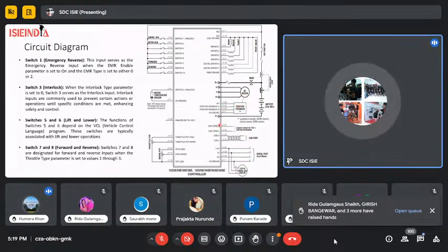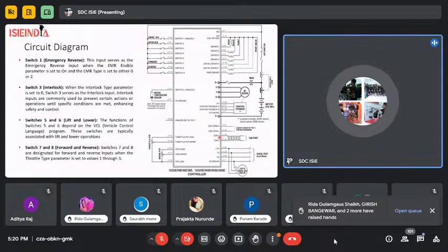Again, the topic: CAN high, CAN low. These wires are going to connect with the CAN communication for data transmission for the ECU controller. CAN high, CAN low also go to the charging function. Like when we connect with CHAdeMO DC fast chargers, they also have priority lines. They have single-phase connections and three-phase connections to charge the vehicle. So we are going to supply the CAN high, CAN low signals, the CAN ports, to them also.